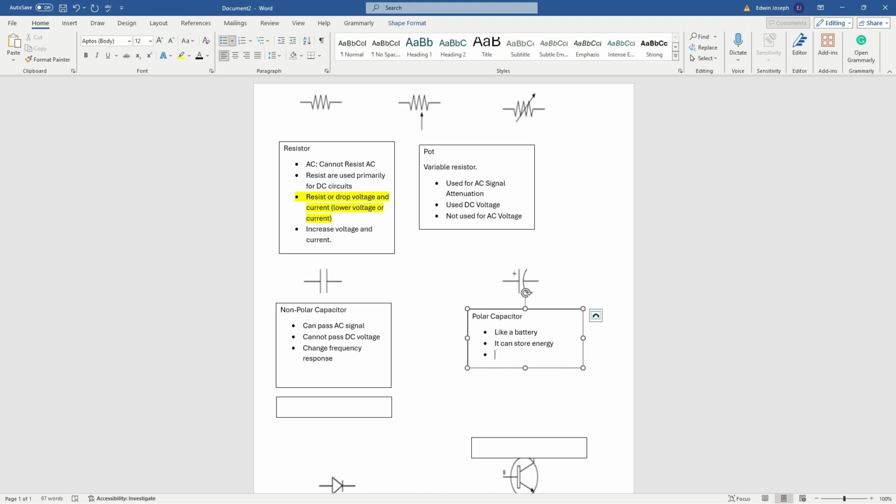A very good example of that, and this is why I said you might be more familiar, even though these are not electrolytic because these are AC. There are AC capacitors used in industrial settings, but they're non-polar, so they relate more to the first area, the non-polar. But you'll be more familiar with AC capacitors in air conditioners and ceiling fans, and they are called starting capacitors. Why is that? Because it takes a lot of power to start a ceiling fan.